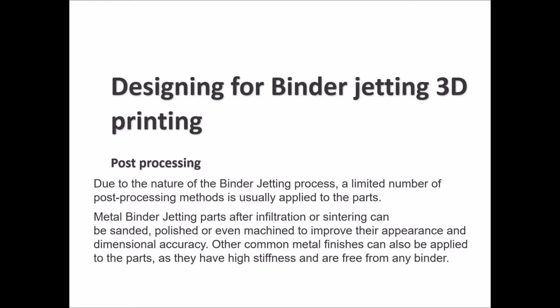For post-processing, binder jetting, we said, is a metal-based 3D printing, so there's a limited number of post-processing methods that can be applied. After you do your infiltration and sintering, you can do sanding, polishing, or machining so that you improve the final appearance and dimensional accuracy of your part. Common metal finishing can be applied as well because it can give you high stiffness and freedom from any binding during application.